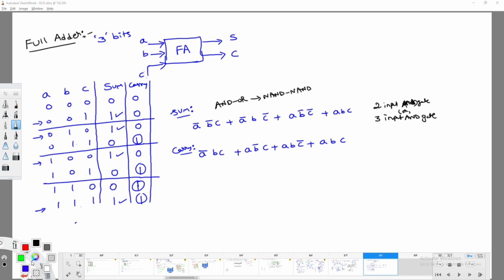See, my requirement is that I don't want to solve it in the form of basic gates. I want to simplify this expression. The same expression, can I write it like this? Sum of all these terms in canonical form, because everything is in the standard sum of products form. Yes, I can write it as sum of 1, 2, 4, and 7.